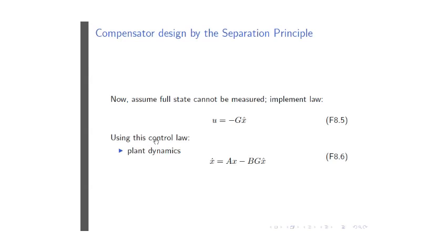Now, we designed our feedback control, in other words, the selection of the gain values in the matrix G. We selected that to have favorable plant dynamics, or to change the plant dynamics from the way it is in the open loop case to some other better characteristics. That's the whole point of having this full feedback design, is to improve the plant dynamics. And we did that by placing the poles at the most favorable locations.